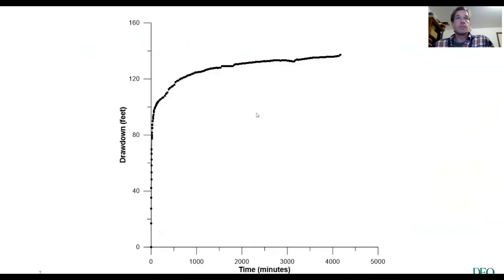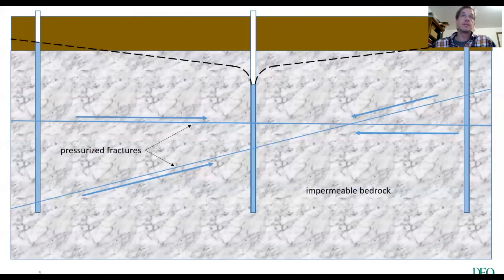So let's talk a little bit about how to analyze data, because you can get a whole lot of information from just the rate at which water level drops in a well in response to pumping, if you know how much water you're pumping or have pumped over time. And it's also very important, if you're going to do this, to pump it at the same rate. And you call that an aquifer test.